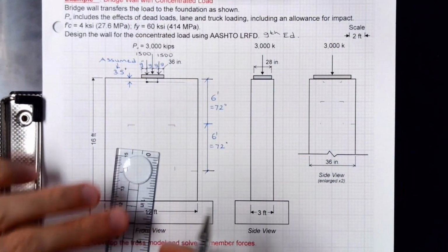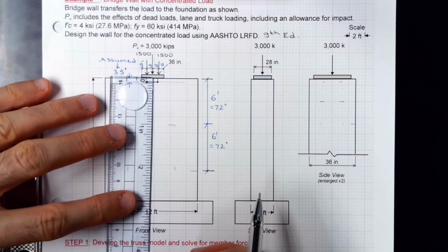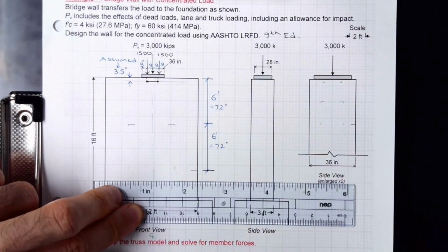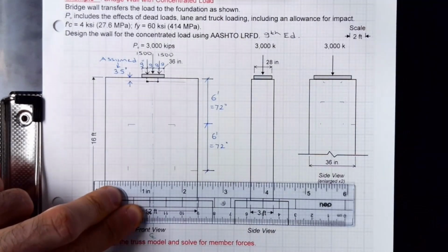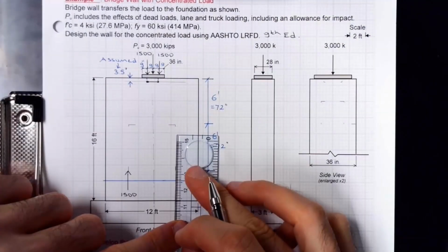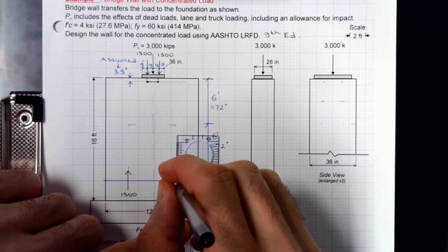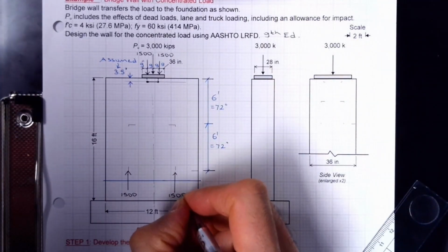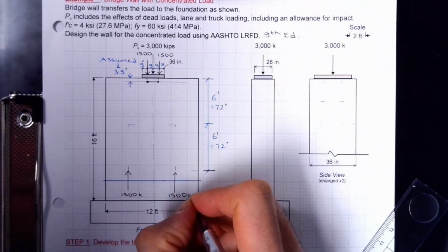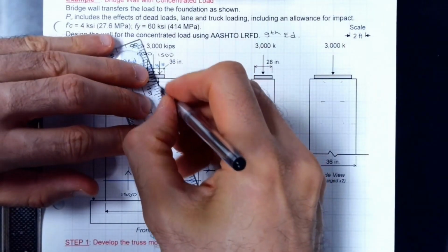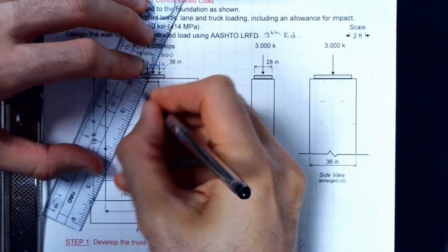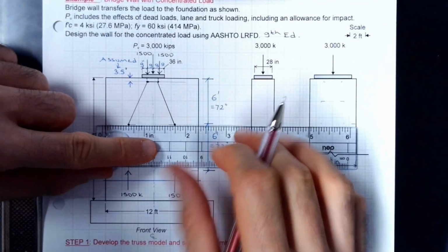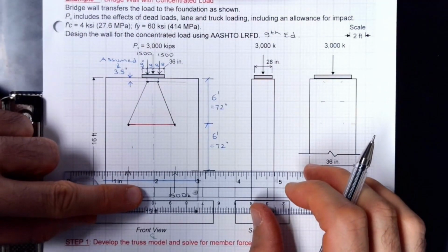At the bottom of it, again, let's just sketch the center line, which I'm going to divide into two, so it's going to have 4 different segments, 1500. At the end of a disturbed region, the stress needs to occupy the entire width, which is what I'm doing in my solution. This would go to this node, this would go to that node. There is going to be the critical tie in between.